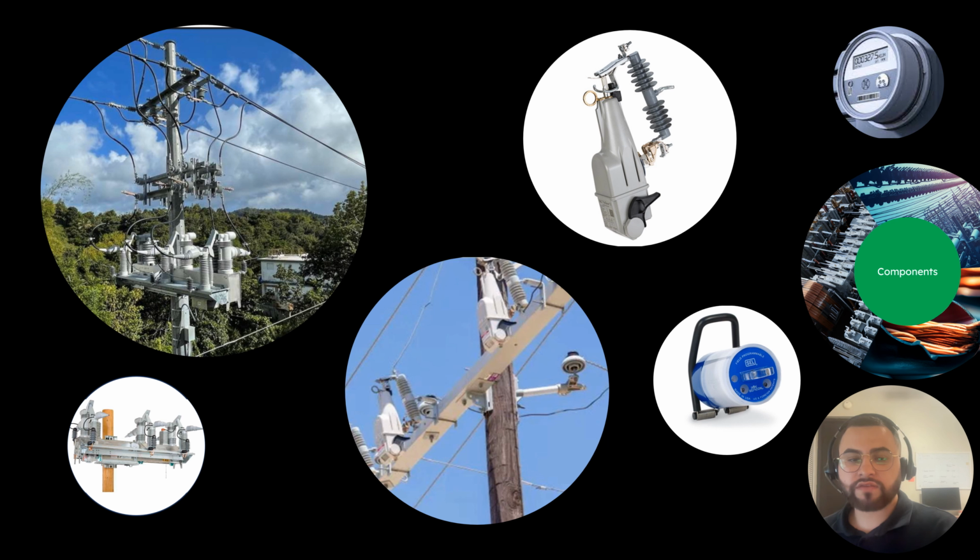We incorporate fuses, breakers, and relays into our distribution systems. These components work together to limit the number of customers affected by a fault. In the continuous effort to enhance the resilience of the distribution grid and reduce outage duration, we implement robust components such as intelligent reclosers. This advanced technology, available in both three-phase and single-phase configurations, plays a key role in resolving challenges within the distribution grid.